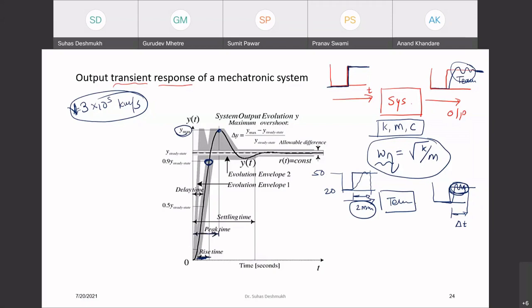Okay, and then due to this peak, it has gone beyond its value. So obviously there will be some kind of oscillations, and it is oscillating and getting stabilized. And this point, where all your oscillations have entirely settled, is called the settling time. And overshoot, I can determine. This is my steady state response. After this, there will not be any kind of oscillations, and that is called the steady state for my system. Okay. And this is the transient state. Okay.